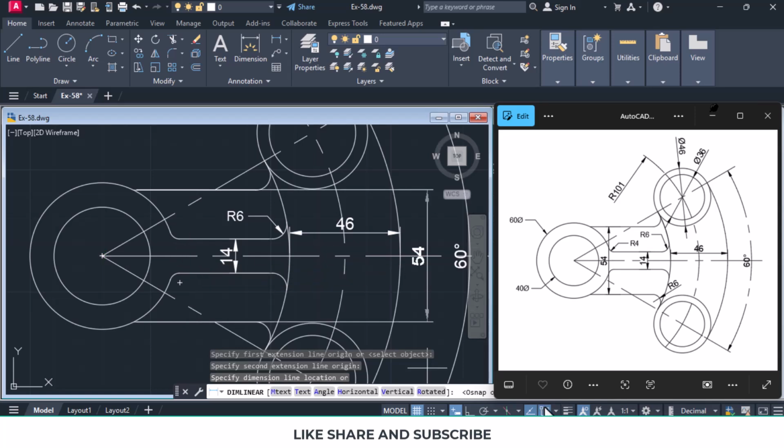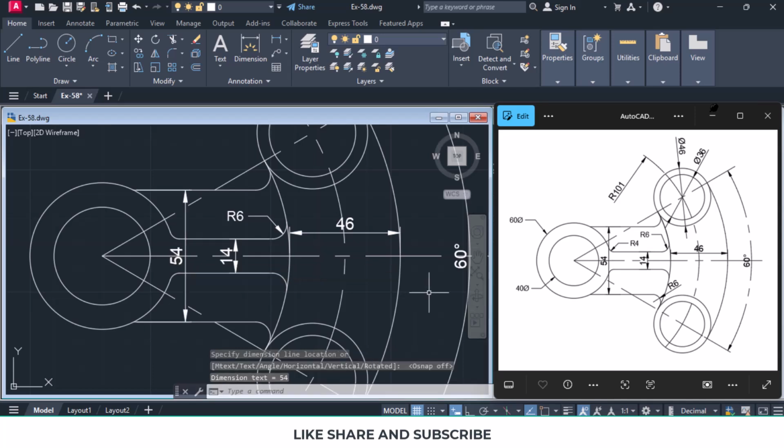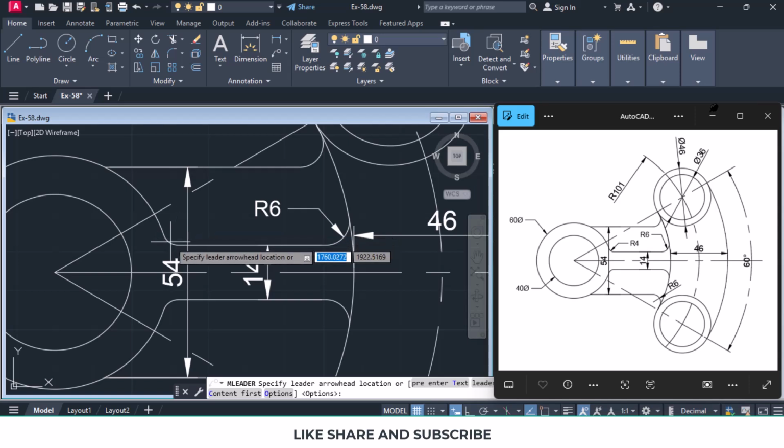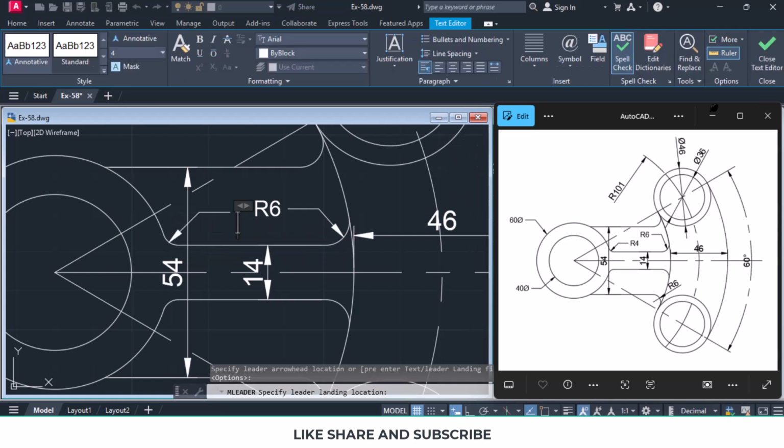You can turn the snap off. So I want it here, 54 units. Now I want to, and I'll select leader and I'll click here. And give the radius as 4 and close the text editor.